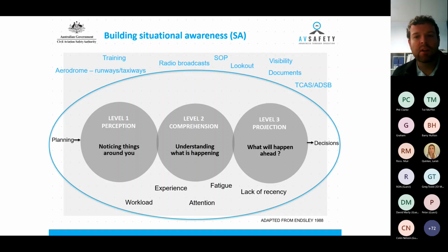The student will do the inbound call, and then you might just ask, what's the overfly height for the aerodrome? And if the student doesn't know, because it's something that they should have planned probably whilst on the ground already, now they're shifting through the air, looking for the overfly height. Whilst they're doing that, they're missing calls. They're not thinking about descending. They're not thinking about how they're going to join the circuit, which runway they're going to use.